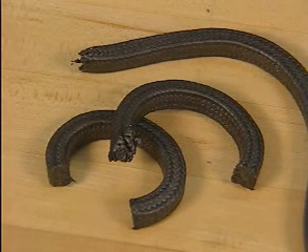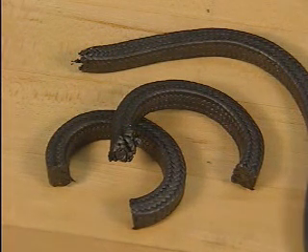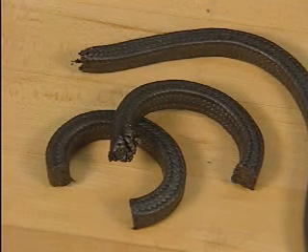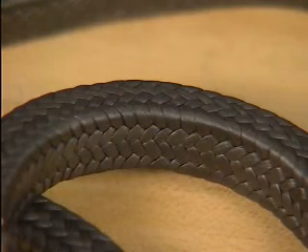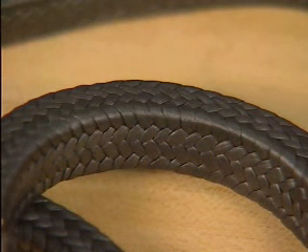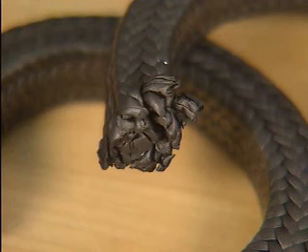Compression packing generally consists of several elements that include a mix of fibers, a binder material, and a lubricant. The fibers can be natural or synthetic, and they're usually twisted, braided, or woven. Binder materials such as grease or wax help to hold the fibers together. The lubricant allows the pump shaft or valve stem to move more easily against the packing, reducing friction and wear. Commonly used lubricants include oils, graphite, and Teflon.